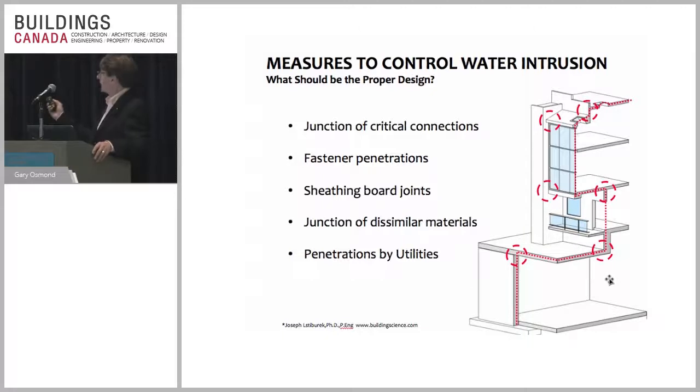My friend Joe Stevebrook, he's come up with this sort of design, and his push was looking at all the connection details, all the joints, because it's at the joints and connections you have a difference of trades, different people walking in with different responsibilities, and "I've done my job, that's good enough, thank you very much, I'm out." That can happen, we have to look at those. So penetration, sheathing board joints, the junction of dissimilar materials, and the junction of dissimilar systems that are intended to keep the water out or keep the heat in.